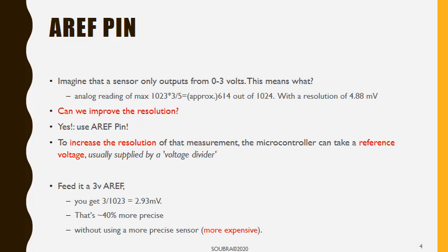What you're trying to do here is to better the length of the step. So 1.5, this is any random value that the temperature sensor could be spitting. In case of 5 volts, no, this is what I'm trying to tell you. In case of 5 volts, you're reading any value between 0 and 5 volts. It could be 2.5, it could be 1.0, it could be 0.5. This is what you're reading from the environment. You're not trying to map 0s and 1s. You're trying to get a voltage into a sampled one. All right, you had a question?